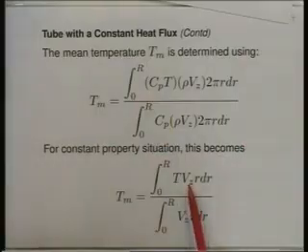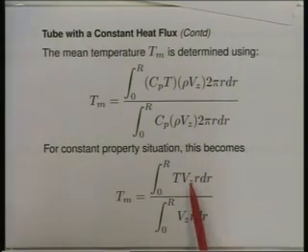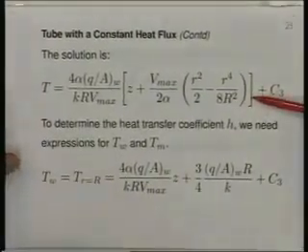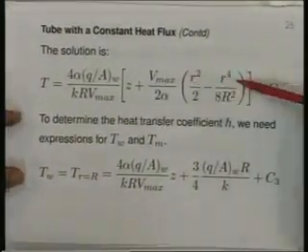Now we have for this temperature, which is a function of R, and Vz, which is a function of R, expressions. Vz is nothing but V max into 1 minus r squared by R squared, and for the temperature we substitute this equation, where the temperature is again a function of R. When you do that, you will get an expression for Tm which looks like this.